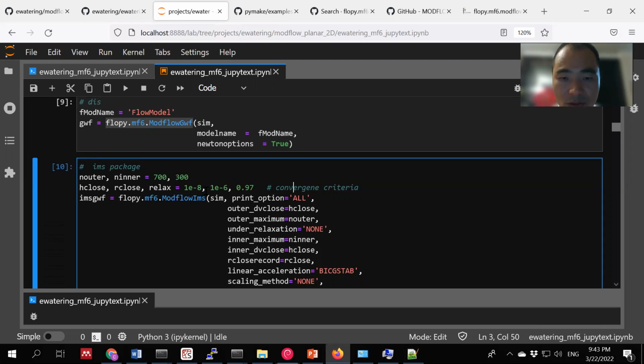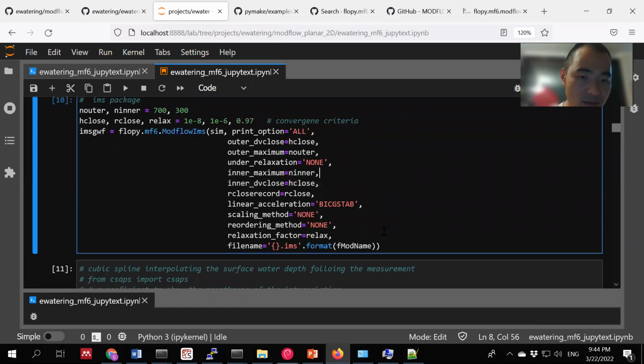The outer loops are all for solving a nonlinear system. So you make a guess for permeability, transmissivity. It's very similar for all the numerical models. So I basically copy and paste the whole thing. As said, when the model does not converge, even if the input looks perfectly okay, that's the moment for us to tune these parameters.